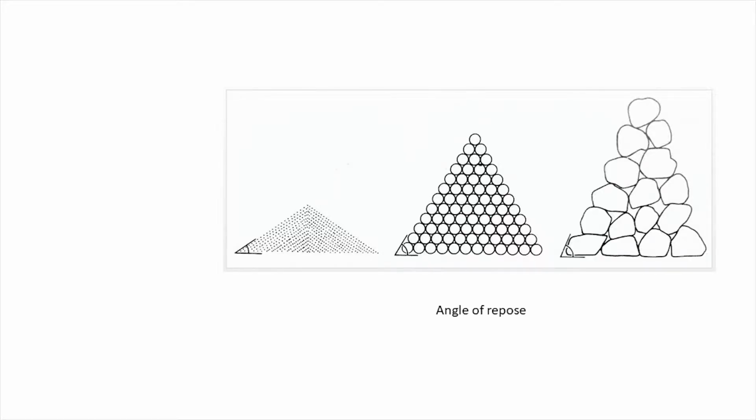Particulate material dropped from a point, like if you took a handful of sand and dropped it onto a flat surface, will form a cone that's characteristic of the material. It's influenced by the grain size, surface tension, wettability, and other factors of the material. The angle at the foot of the cone is the repose angle, and in the round we have the repose cone. And this is the configuration to which nature wants the material to go. Gravity wants it to take that form and no other form. Now, bear that in mind.